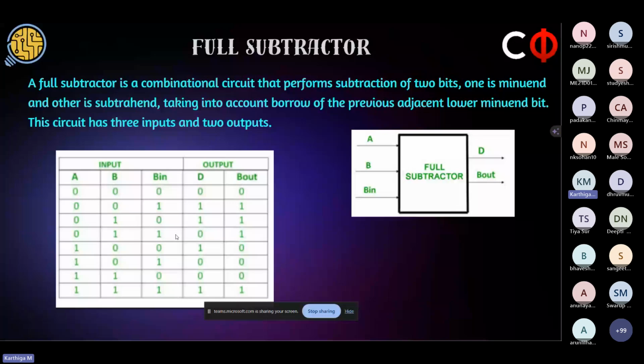Why? Because a very similar procedure as in a binary adder can be seen in a binary subtractor as well. The borrow input will be moving on to the consecutive full subtractors. So that's why we call this borrow input. So you have 0 minus 1, you will have difference 1, borrow 1, and then you subtract and you have another 1 in B in. So your difference will be 0, B out. You can just go through the truth table. It's quite easy.